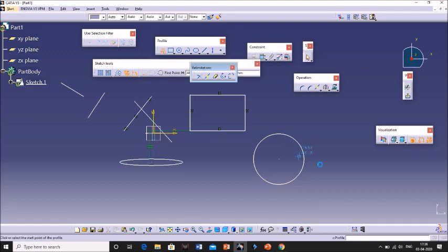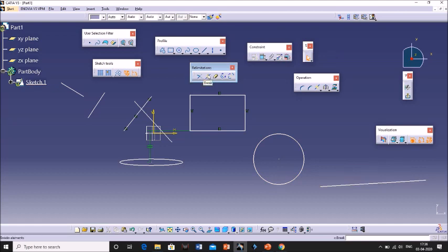So once again I'm explaining. Draw a line, select the break option, select the figure and specify a point. The point we have selected will divide the object into two parts. So this is related to the break point. It is applied not only to a line, but also to a circle. Select the circle and specify a point. So it is one part, it is another part. Like this the object is broken at a specified point.